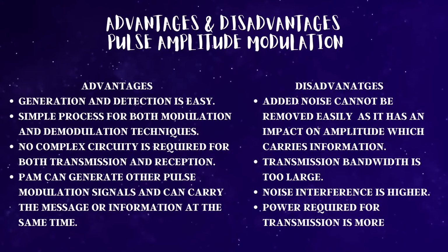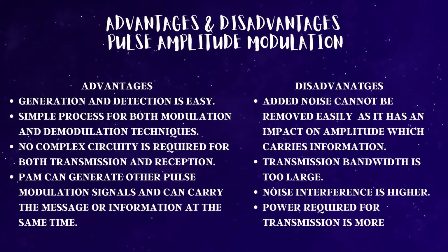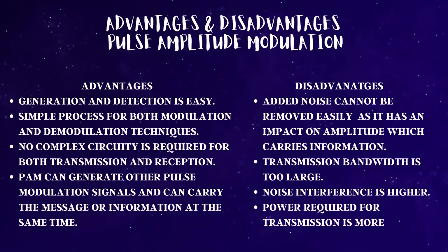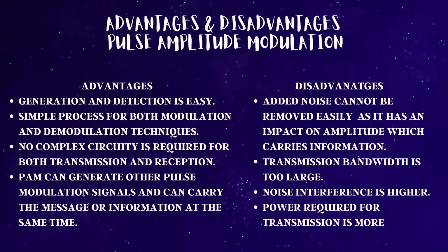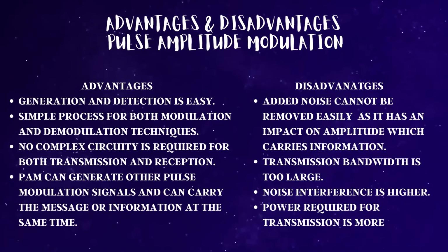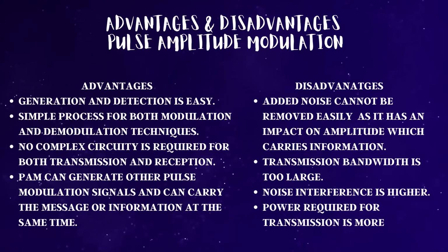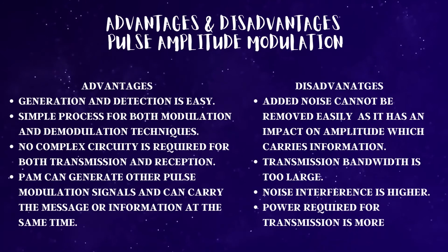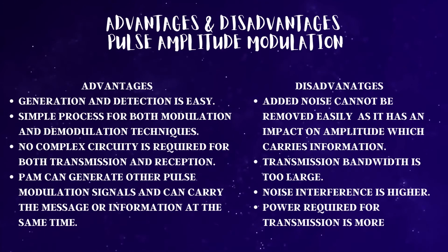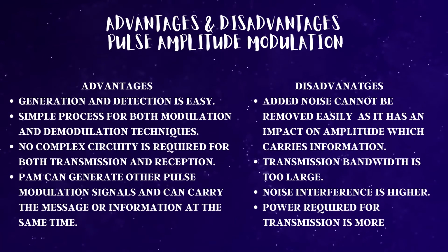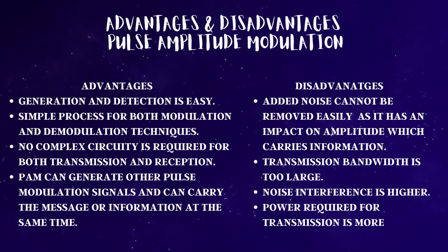So the disadvantages are, first, noise cannot be easily removed since it affects the amplitude which conveys information. Next, the transmission bandwidth is very large. Besides that, the level of noise interference is higher. And finally, the amount of power required for transmission is higher.